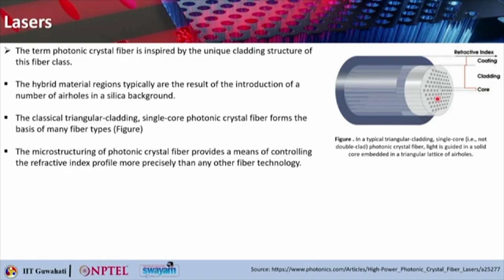The microstructuring of the photonic crystal fiber provides a means of controlling the refractive index profile more precisely than any other fiber technology. Right here, you can actually change the periodicity or the pattern of the holes or the dimension of the holes, and that can give you different types of index profile.